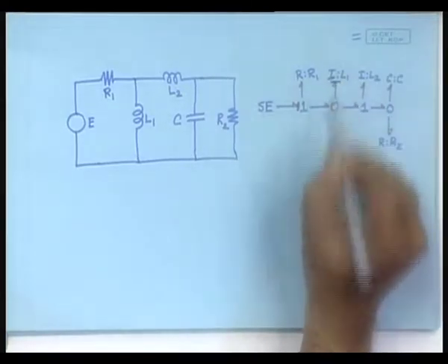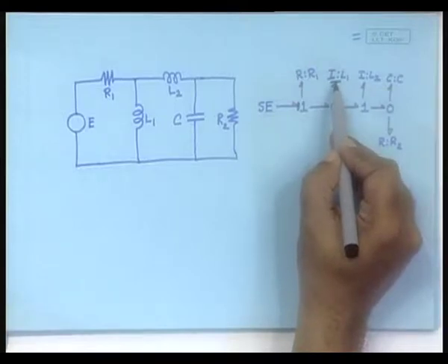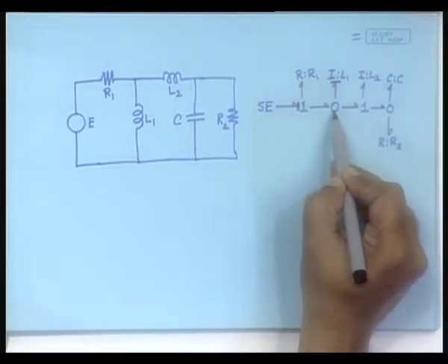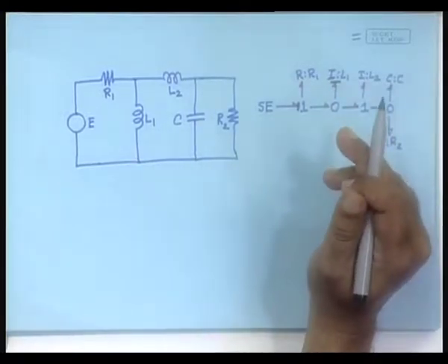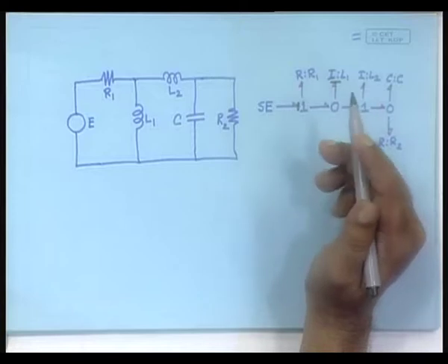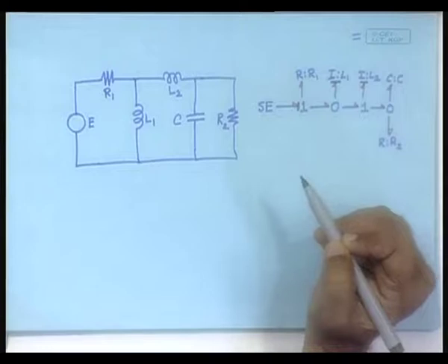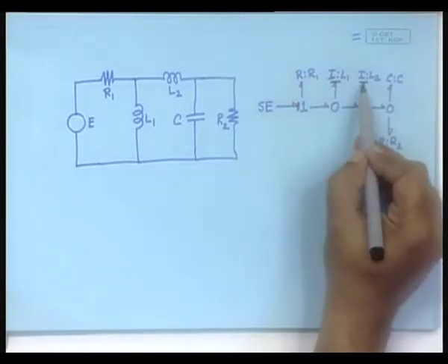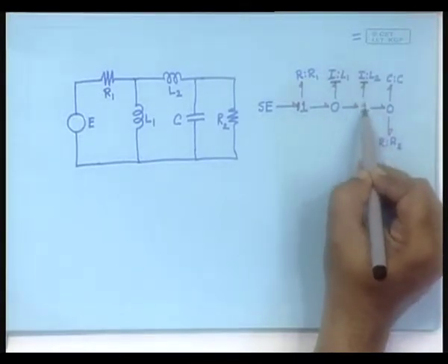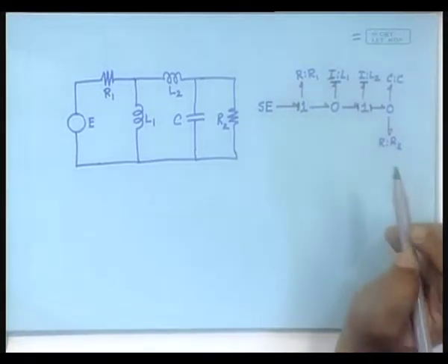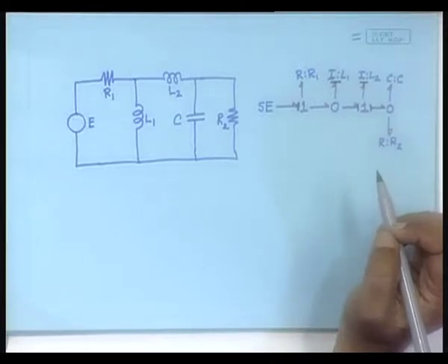So, here we will first put this which means that the I element is receiving the effort information and giving out the flow information, and it has come to the 0. It is not yet causal, because 0 will be completely causal if a strong bond brings in what information? Effort information. Okay, so let us move to the next one. Here let us put, the moment you do that, the flow information has come into the one junction, and therefore the flow information must go out of the one junction. So, these two are immediately causal. Fine.